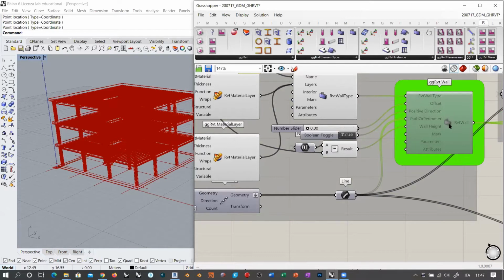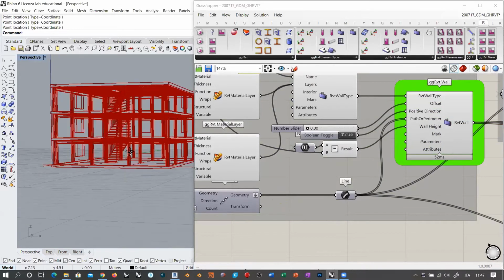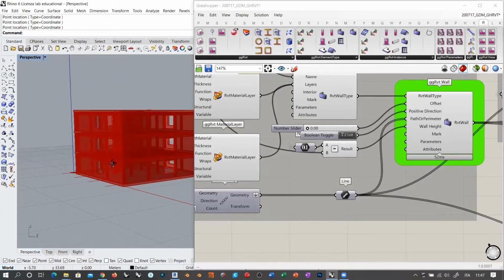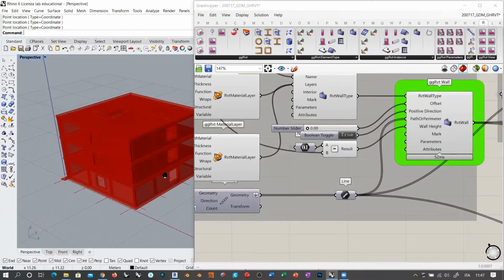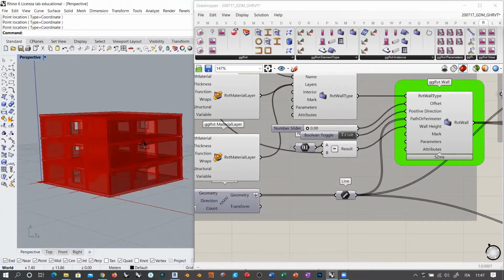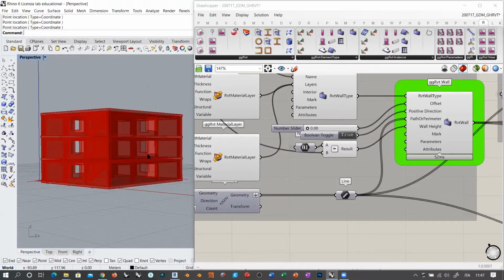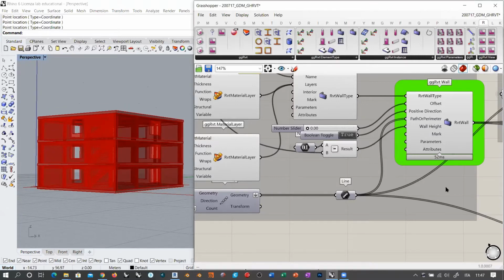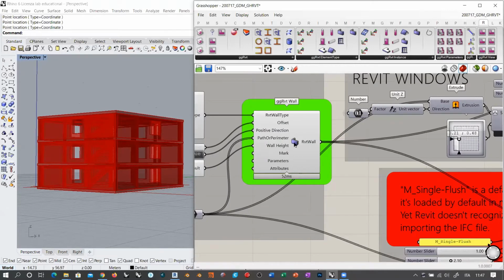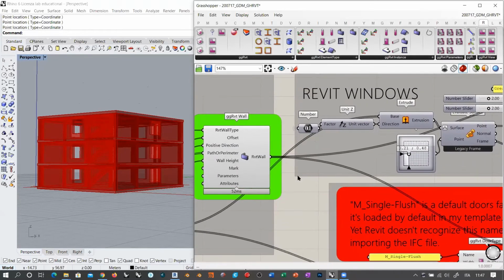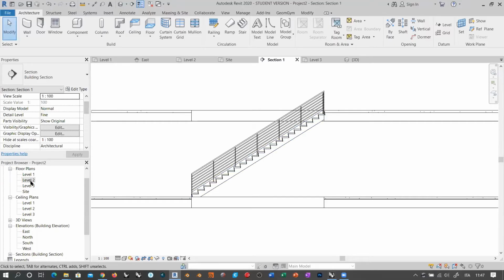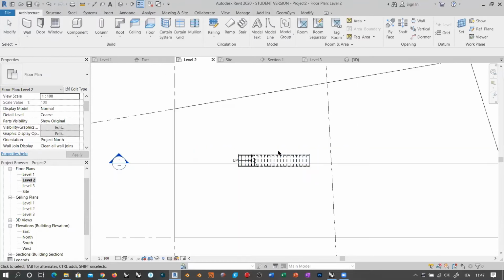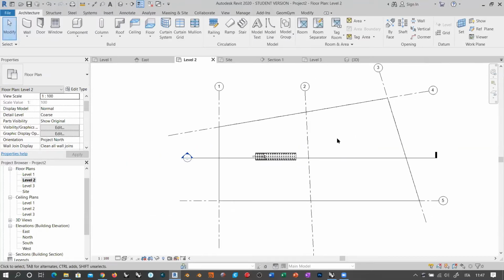Now, if I turn on the preview of this, you see that I not only have the linear walls already visible, I also have windows. Now, this is another situation in which what happens next affects what comes first. It's something counterintuitive for Grasshopper users, but this is how this thing works, because once you have defined the wall, because we have hosted elements, so a window, if you go inside Revit, and I go inside, for example, level 2 viewport, there is no wall here. There are only floors and stairs, okay?